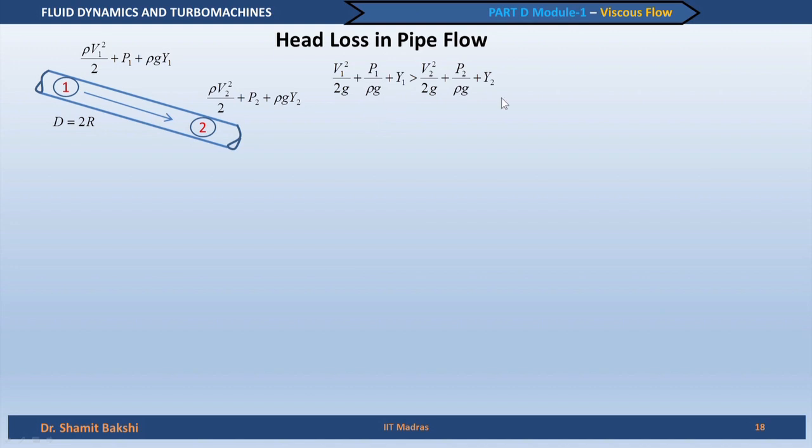But we can convert this inequality into an equation by introducing this as an extra term on the right hand side. So, this is like the head loss due to friction, and all this energy per unit weight actually has, you can check on your own, a unit of height, and that is why we say head loss, or this is represented in terms of height, in length scale.